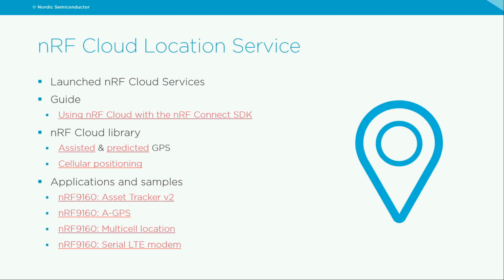To get a position, the GPS needs information such as the satellite orbital data, exact timing, and rough position estimates. GPS satellites broadcast this information in a pattern which repeats every 12.5 minutes. Meaning that if you are to get this data directly from the satellites, it would take a lot of time. The assistance service basically offers you to download the same data through the LTE link instead, meaning that it will go much faster.